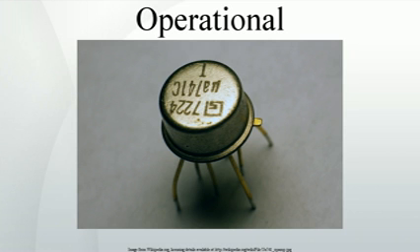Architecture. A small-scale integrated circuit, the 741 op-amp shares with most op-amps an internal structure consisting of 3 gain stages. The differential amplifier, outlined in blue, provides high differential amplification (gain), with rejection of common mode signal, low noise, high input impedance, and drives a voltage amplifier, outlined in magenta, which provides high voltage gain and a single pole frequency roll-off, and in turn drives the output amplifier, outlined in cyan and green, which provides high current gain, low output impedance, along with output current limiting and output short-circuit protection. Additionally, it contains current mirror bias circuitry, outlined in red, and a gain stabilization capacitor, 30 picofarads.